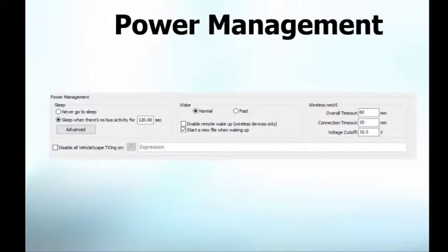And then power management. So a neoVI Ion with, let's just say you load it up, you've got 2 Fire 2 VNets in here. It's going to run about an amp in your vehicle. So obviously that's not something you want on when the vehicle's not on. So by default, this is actually not default off anymore, it's now default on. We have power management options. So the default option is after 2 minutes of no vehicle network traffic, we shut down. We go into a low power state.